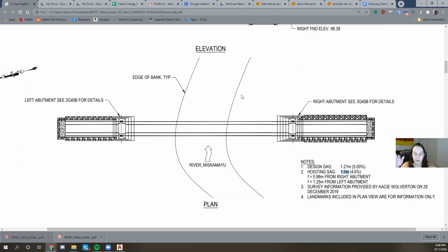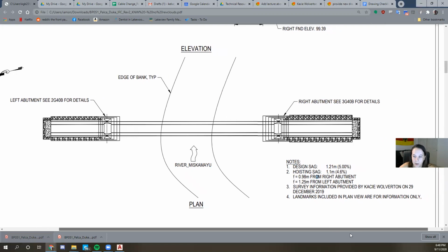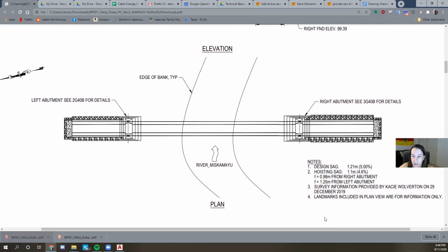Depending on which side you're able to look at, because you'll want to look at the line and then pan to look at the cable. That's why it's important to provide that low point from the right and the left, or the high and the low side. The low side's easy, it's just equation 5.3. The high side is equation 5.3 plus delta H, because that's how much it's sagging plus the difference between the two saddles. If that doesn't make sense, please feel free to ask questions. And that's what we do with hoisting.